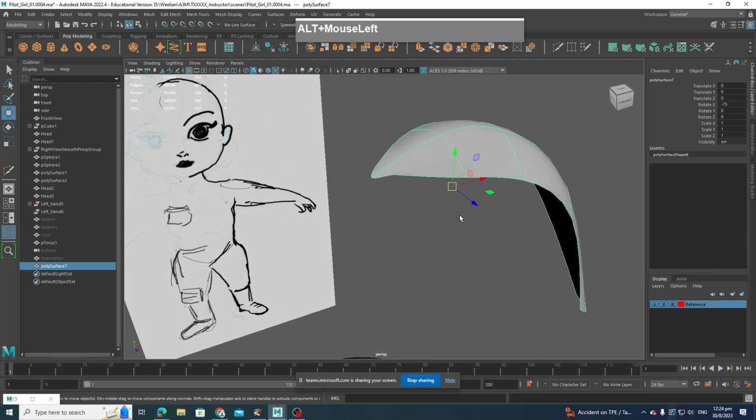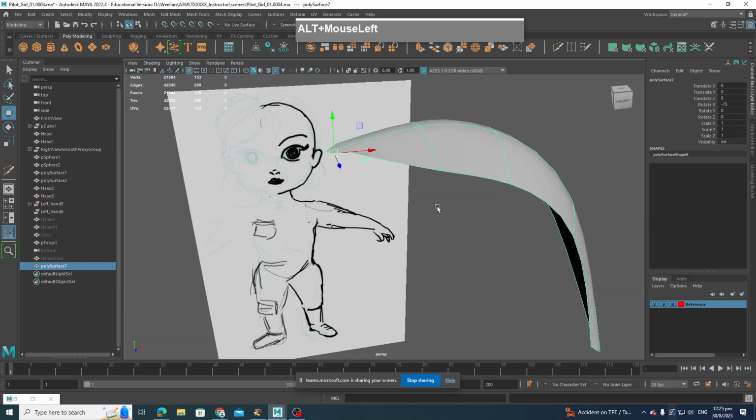Okay, so you have to press D to go to the pivot manipulation mode, then holding down V, then click here. Right now I can't transfer it over here because the snap is not activated, so I'm going to right mouse click on this, snap pivot position, then holding down V, and then left mouse click, then you will move over here. Then I need to reorient the orientation of this pivot point. So right mouse click on it and then say reset pivot orientation. Once you press D to get out of pivot orientation.